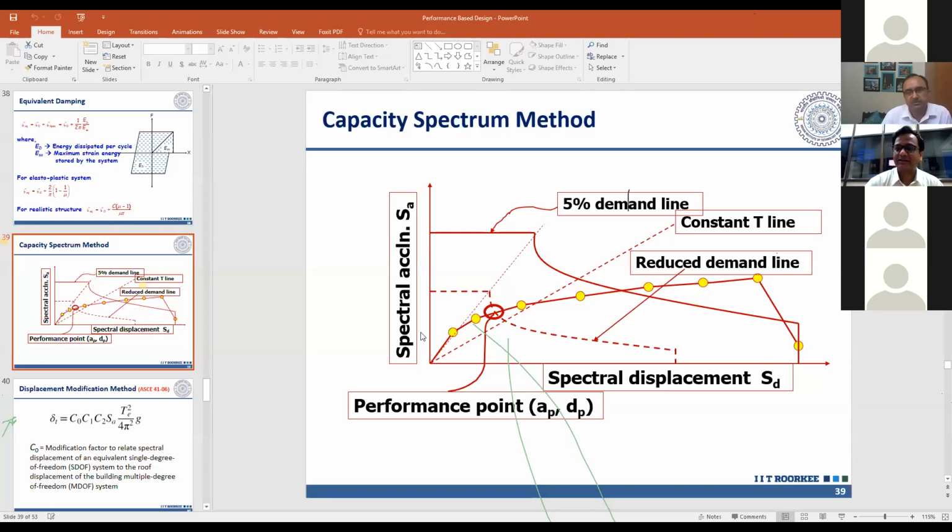The next question is, while developing fragility curves, what shall be the effect of eccentricities on the different performance levels, mainly for asymmetric buildings? When the building is asymmetric, it will have additional deformations because of the torsional response.